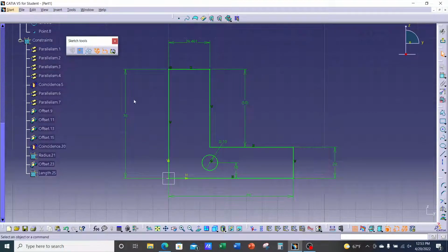Okay, so anytime you have a sketch turn magenta or purple on you, start at the bottom, look for yellow swirls, and start deleting the constraint. And then you may need to add new constraints to get rid of white geometry, right? Anytime a piece of geometry is white, like again, if we don't have a diameter, I'm going to delete this diameter. If it's white, it means it hasn't been defined, right?